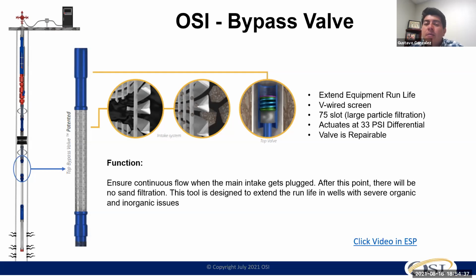The majority of the people, again, we try to go with either tungsten or some ceramic, or I have been seeing some people do some zinc coating and stainless steel coating on the outside. It depends: some people may be facing sand, but also H2S, and now they start seeing holes in the housings. So there is not a right or wrong answer.